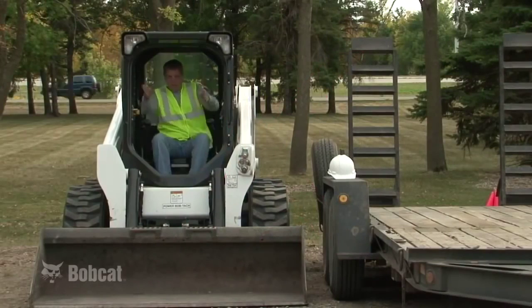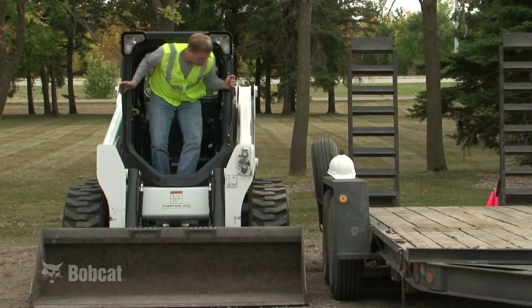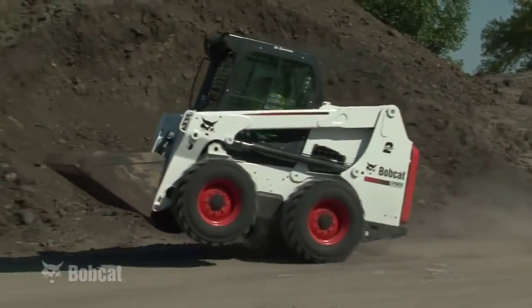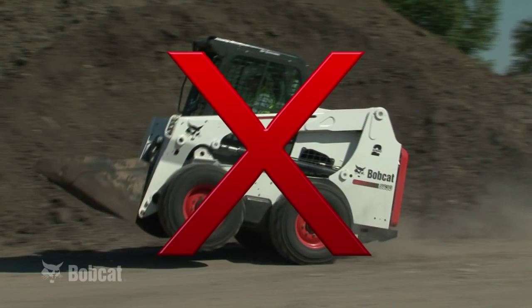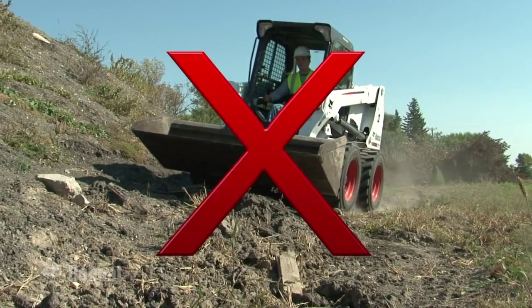Never stand, lean, or reach out of the front of the loader when the engine is running. A steering control or hydraulic control could be activated. Don't make any sudden stops, starts, or turns. Again, operate the controls smoothly. Avoid rough terrain if possible.